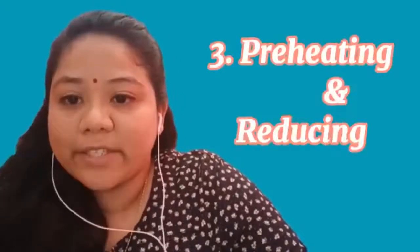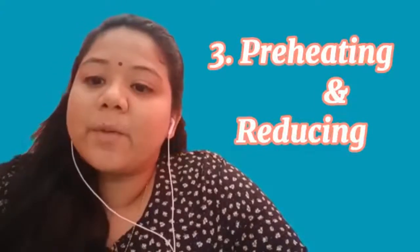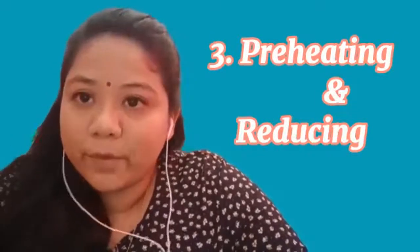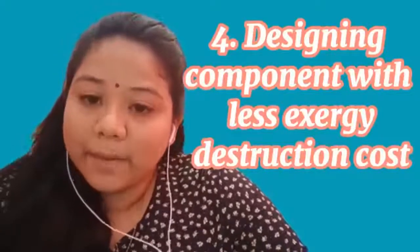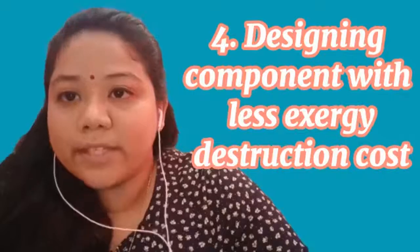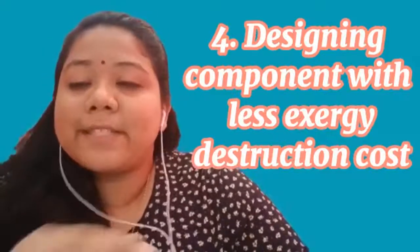The power plant components that should be considered for improvement of efficiency are the boiler and turbine. The exergy destruction in the boiler can be reduced by preheating the combustion air and reducing the air-fuel ratio. Designing the boiler and turbine with less exergy destruction cost will enhance the steam power plant's performance.